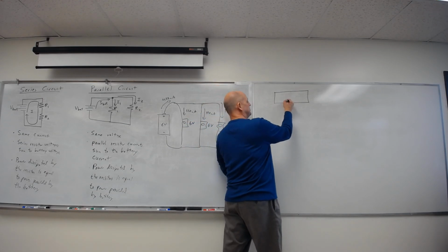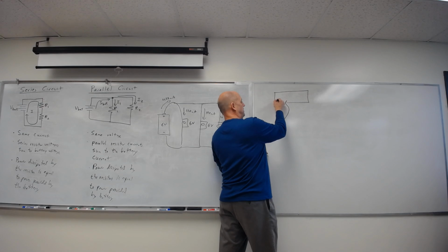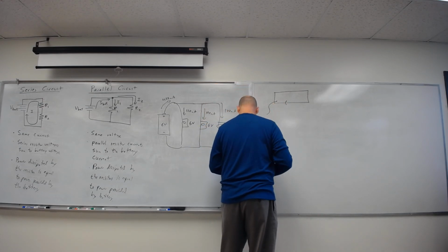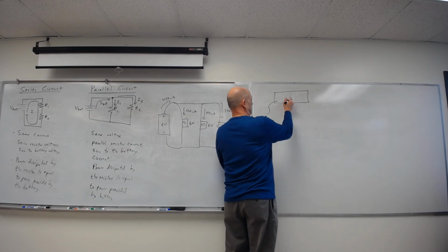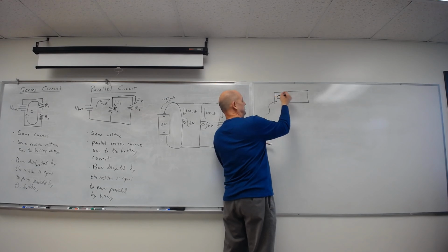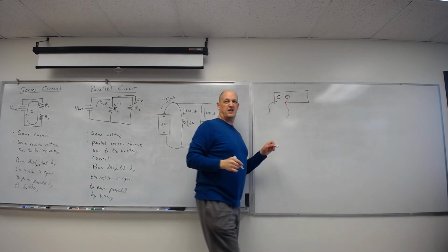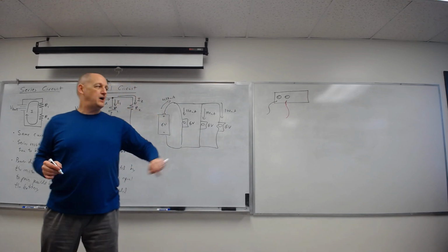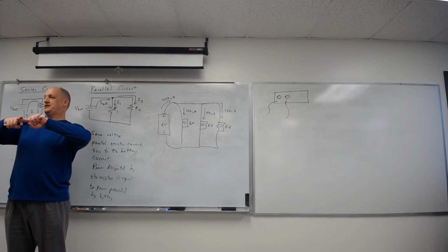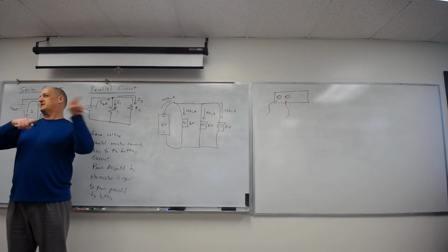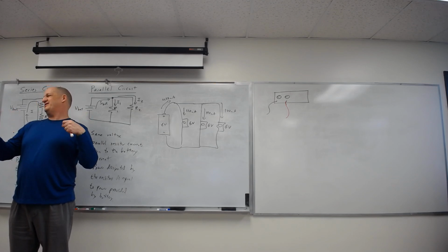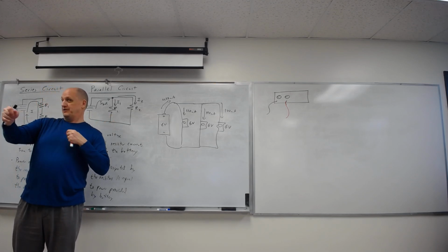And the red, you can connect your little red wire and come out, and the black wire. Reminder, you've got to turn the little current knob up a little bit so it can provide current, and then turn voltage up. But I'd connect that first. Do not let those two ends touch. Somebody yesterday was not getting their voltage up because they had the two ends touching. It was just laying over the side. It has short circuit protection, but still. Hook it up first, then turn your voltage up. That way you make sure you separate those two bits.